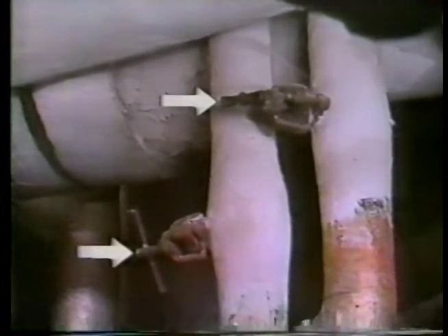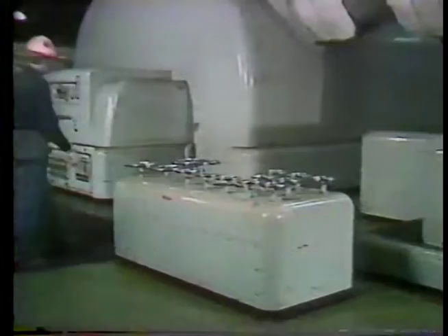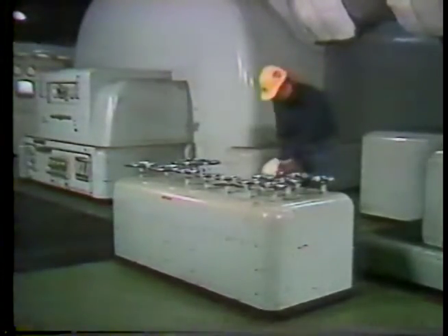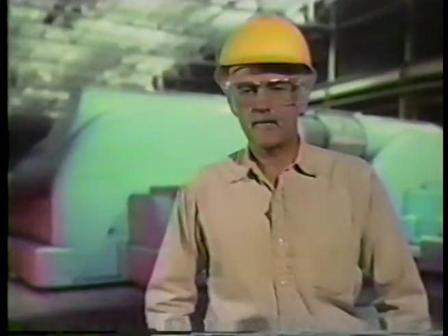Startup drain valves are operated either manually or by motor. Some drain valves are operated locally at the drain, and some are operated remotely from a centralized valve pedestal. These hand wheels are connected by linkage to the startup drain valves. If startup drain valves are motor operated, they can be controlled by the operator or by an automatic control system.